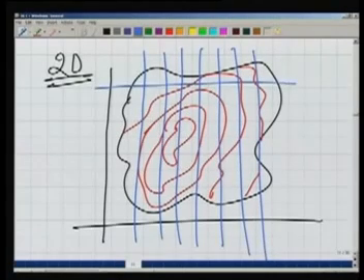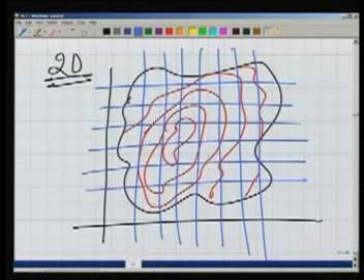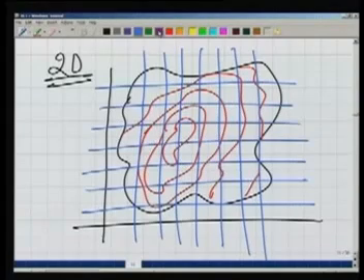The contours are shown here only to show you that there are undulations in the ground. Now for each grid cell, we can write a particular height value. Depending on the contour here, I will give a height value, H1 or H2. So this H2 will be the average of this contour and this contour. Similarly here, H3, H4, H5, and so on, maybe Hn.